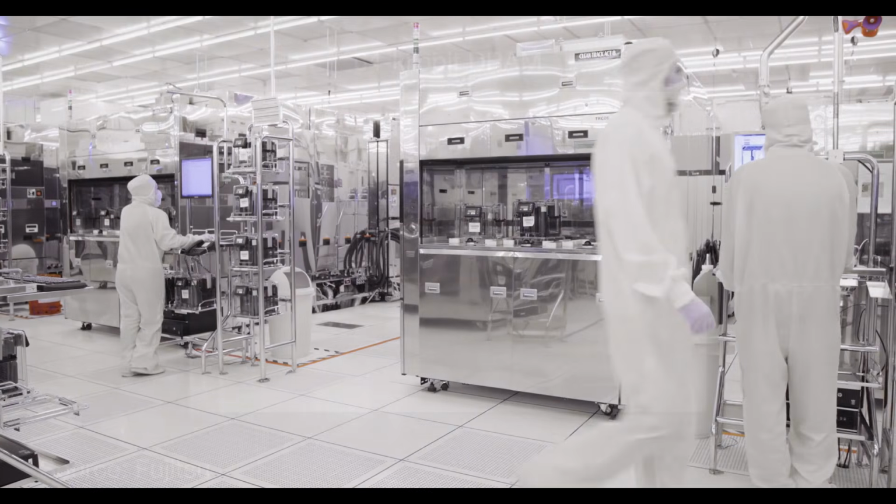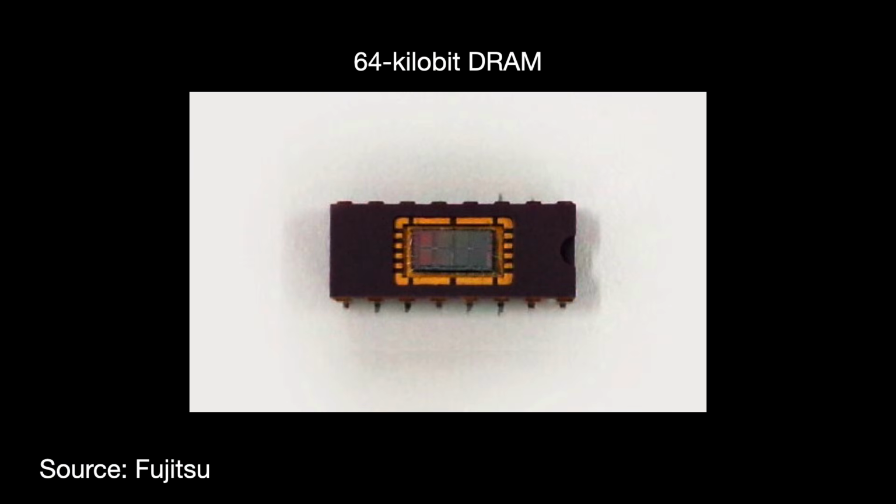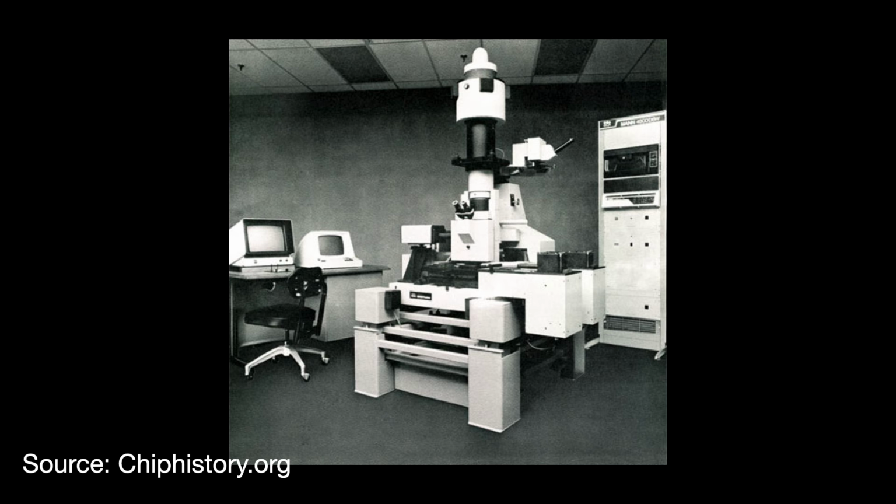Improvements in lithography equipment, encompassing machines that do exposure, resist processing, and etch, have largely driven the upper limits of complexity for semiconductors since the late 1970s. When those lithography advancements stall, it filters down the chain. In the early 1980s, Intel needed to produce their own 64 kilobit DRAM chip. The standard lithography tool back then was the projection aligner. These tools projected a chip design across a whole wafer. However, the 64 kilobit needed more resolution than the aligner could provide.